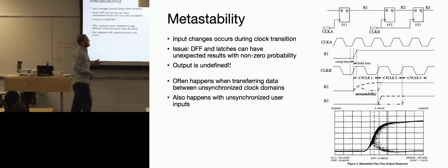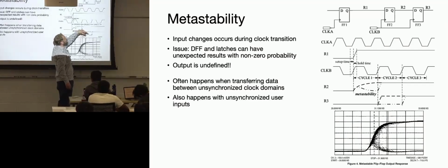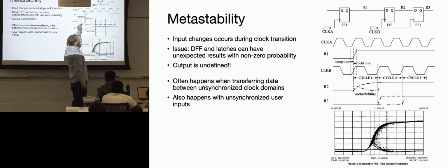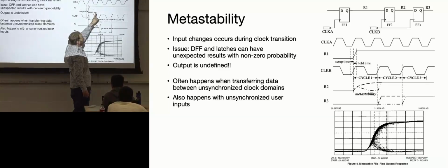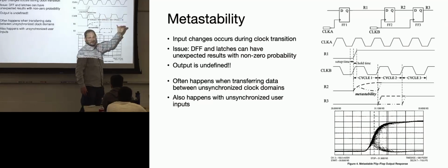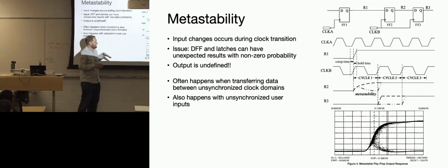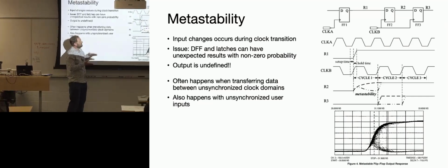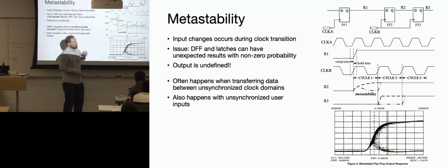The way around that is that you put two D flip-flops in series with each other. The likelihood that it breaks or has an issue with one D flip-flop is low, but still there. But the likelihood that the error will propagate to the second D flip-flop is very low. So that's the way they get around it. You have an input, you don't want this metastable state, metastable meaning between two states, propagating and corrupting your system, so they put two D flip-flops.